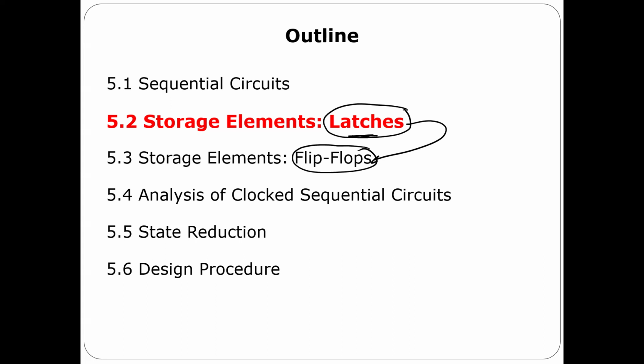Again, to make it easy: for a sequential circuit, we need storage units to store the state, because the output does not only depend on the input, but also depends on the current state. And the circuit should change states, I mean state 0, state 1, state 2, state 3, and so on. These states are stored by storage units. A storage unit can be a latch or a flip-flop, but most of the time we use flip-flops. But anyway, a flip-flop is actually built from latches.